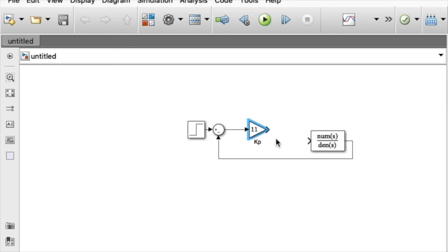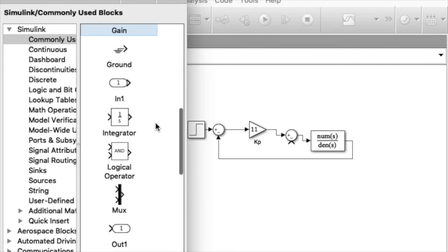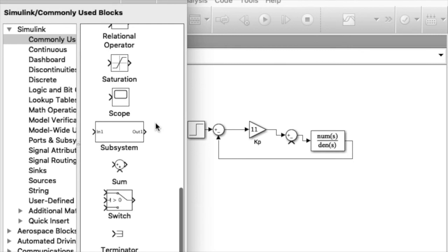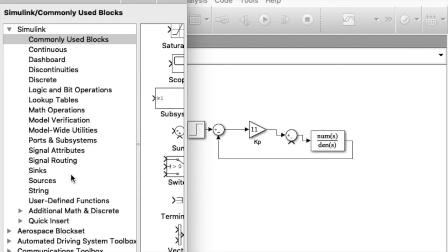so then we also need one more summing here, because KP comes from here, and we'll get the KD also from here. So for KD, we need minus KD into S of, so let's see if there's a differential function which can give me a, so 1 by S is there. Do you see a differentiator? I'm doing it first time implementing PID in a Simulink.